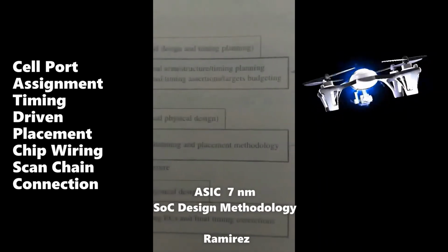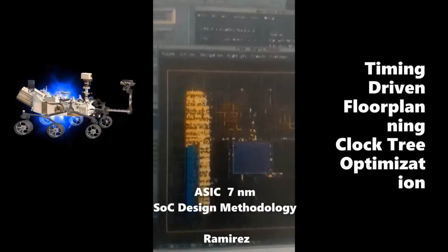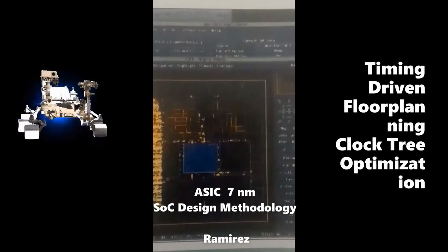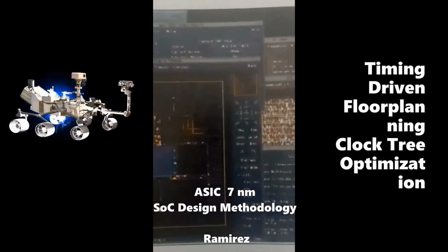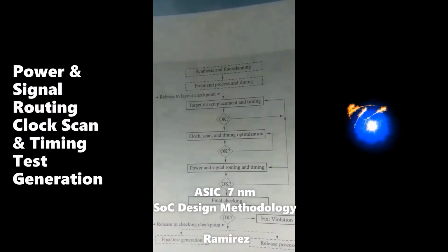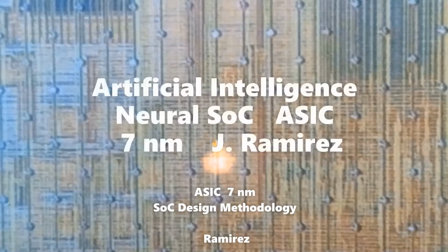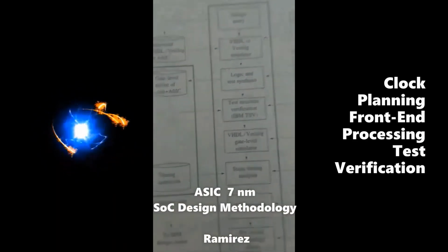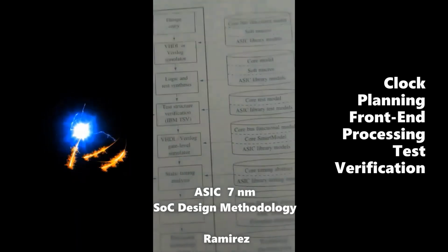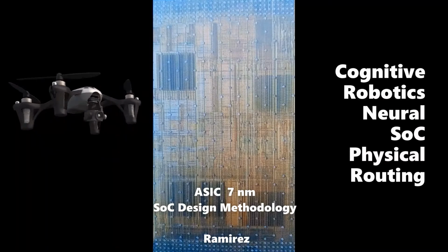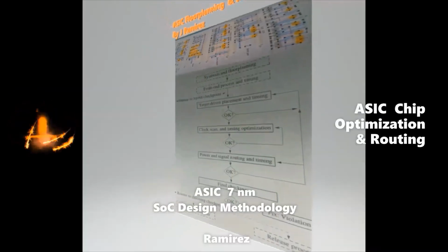Second, generate constraints for placement on the basis of a timing analysis done using idealized clock arrival times, latches, and estimates of wire load and RC delay before the physical design. These constraints include limits on the capacitance of selected nets and limits on the resistance of RC delay for selected connections.